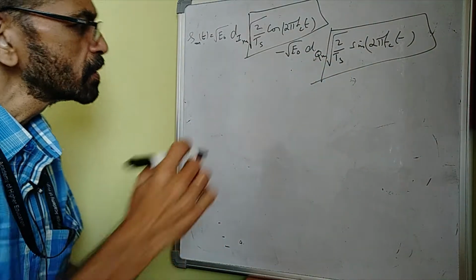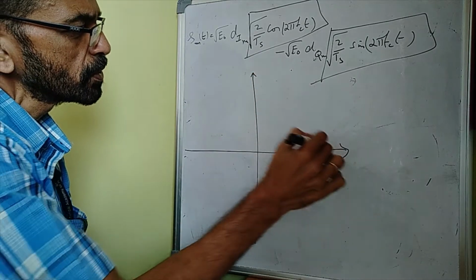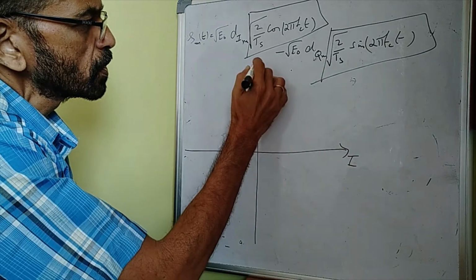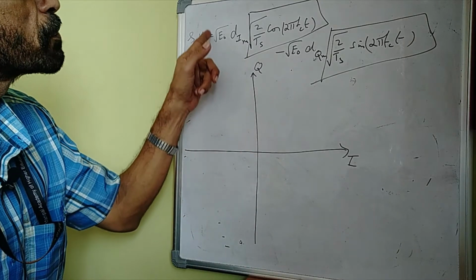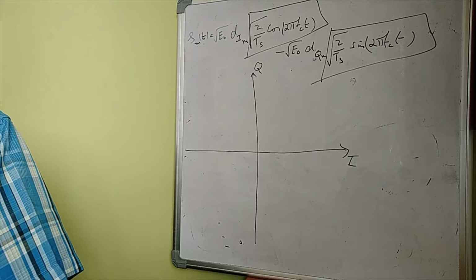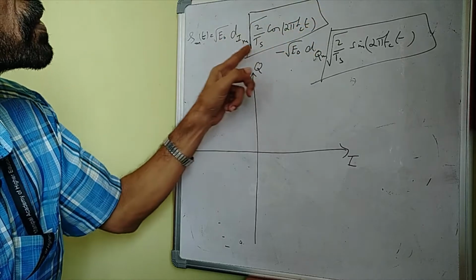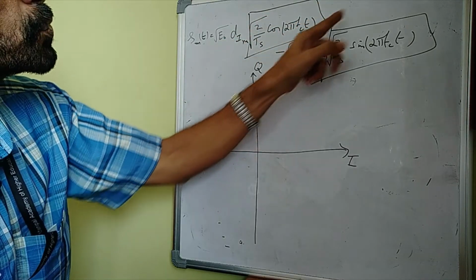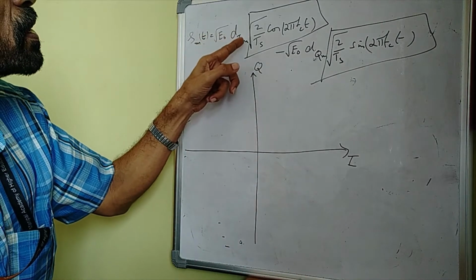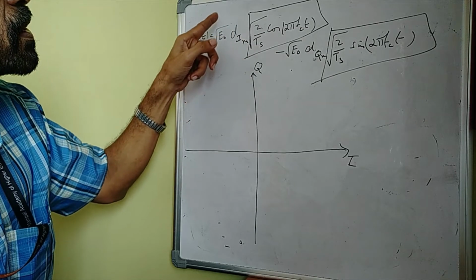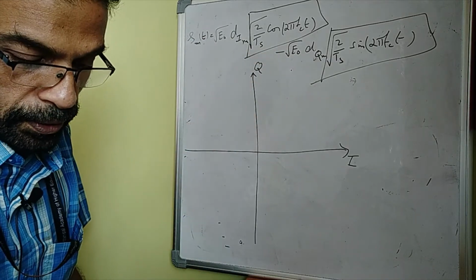So it's again a two-dimensional signal space, in phase quadrature axis, or phi 1, phi 2. Phi 1 is the in phase carrier component, and phi 2 is the quadrature carrier component, and these will be the coordinates, so to say. So that includes the negative sign.